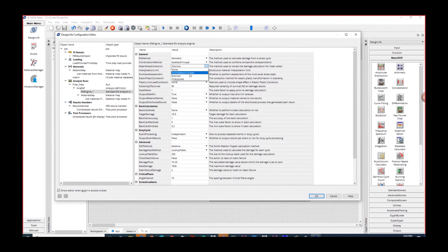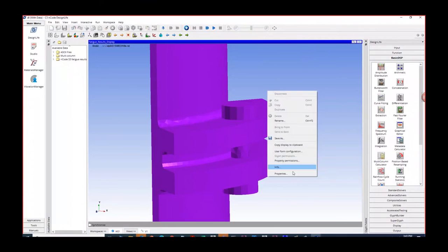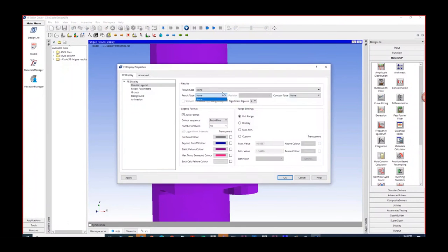Ansys provides these three methods. You can choose one of them, and also use an appropriate plasticity correction. Again, you can refer to fatigue textbooks and understand the logic behind Hoffman-Seeger and Neuber, when what is applicable and so on. Okay, and we get meaningful results like what we are seeing here.